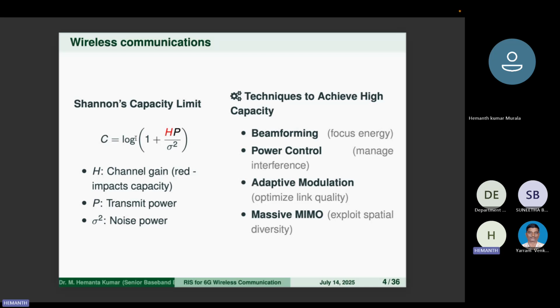The complete equation becomes H times H Hermitian H inverse H Hermitian, into X, plus noise. Agree, everybody? Get it? Then what about this value? What is this value? This is mathematical: H Hermitian H inverse H Hermitian into H. What is this value?